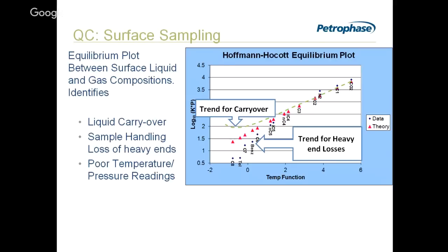So that would be typical for a very hot separator, where we've actually lost some of those components because the sampling equipment was cool and we don't have the capacity to really roast those up to try and get them single phase again in the separator. But here's the thing, because we know what they should be theoretically, we can actually correct for that. So this is a really useful tool, because it not only shows if the compositions are consistent with the separator conditions and are correct, but if they're wrong, in many cases you can correct them, which is much better than you can say for the constant volume depletion study.